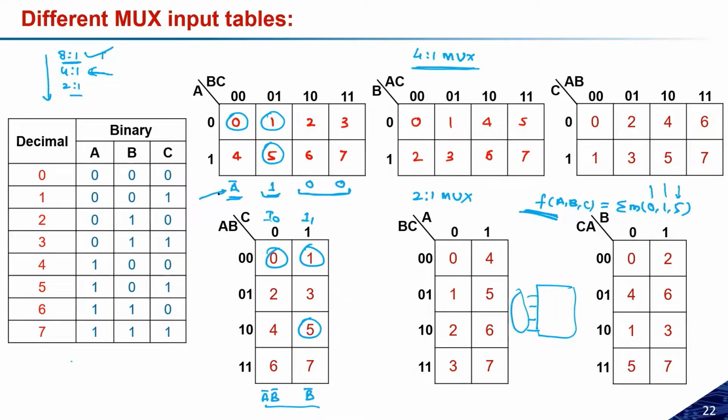But if you see the internal hardware requirement, the 8:1 multiplexer requires at least double the number of logical gates inside the module compared to 4:1. So the total area penalty, if we consider the internal and external both, the 4:1 may be the optimum one. Considering the 4:1 multiplexer to design the same function will give you overall less area penalty than 8:1. Please recall what I'm saying. This is really very important to understand.